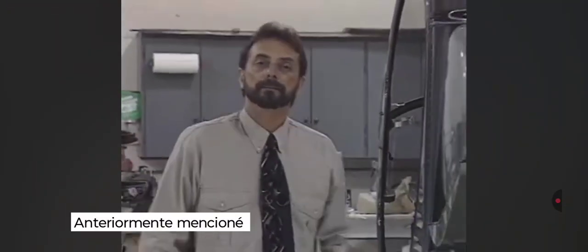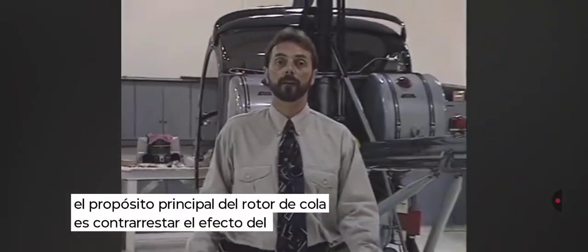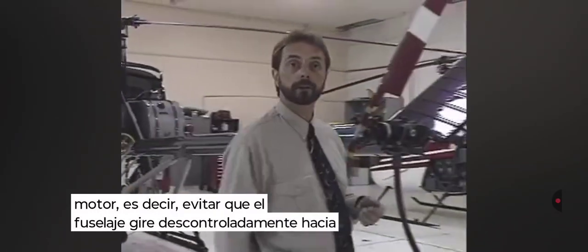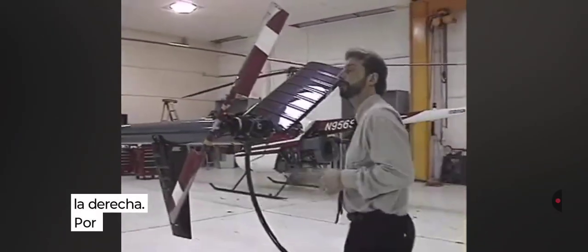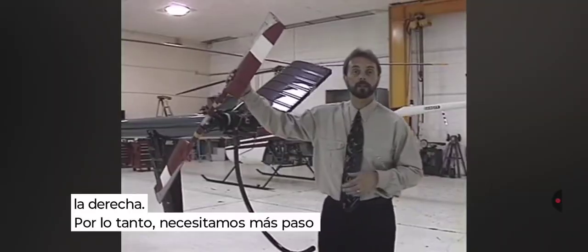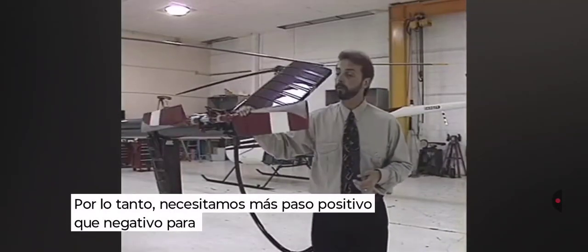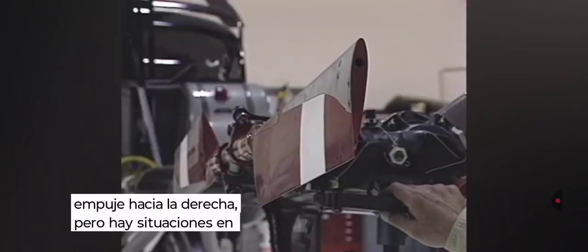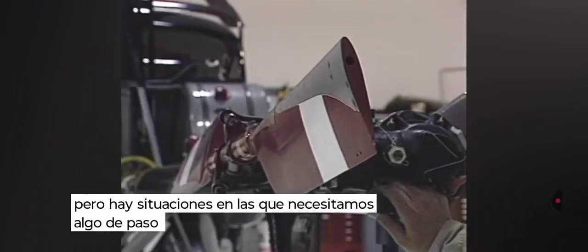One other thing. A moment ago I said that the primary purpose of the tail rotor was to counteract the torque effect of the engine. That is, to prevent the fuselage from spinning wildly around to the right. So, we need more positive pitch available than negative pitch in order to provide thrust to the right. But there's a situation when we need some negative tail rotor pitch.